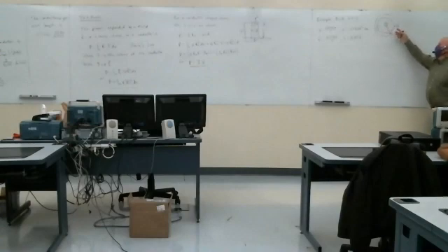So here we actually have two conductors, and they would actually be in series. In the coax, the current flows along the inner conductor and then back along the outer conductor to whatever the load is. So we want to actually add these two resistors together so that they're not really in parallel.